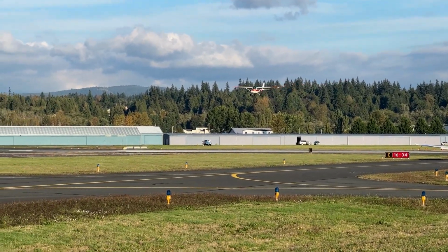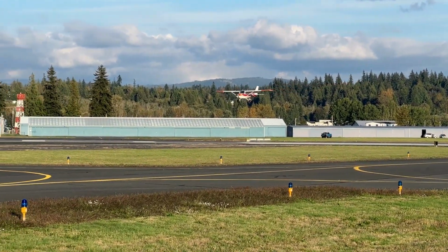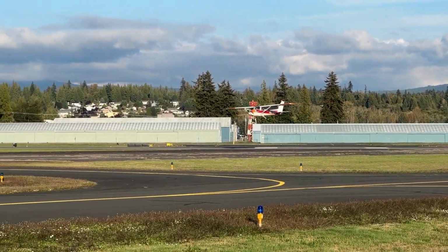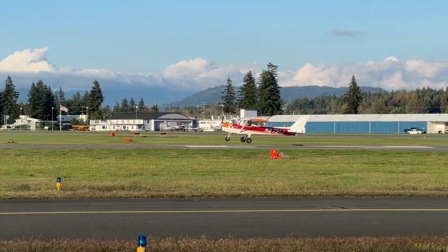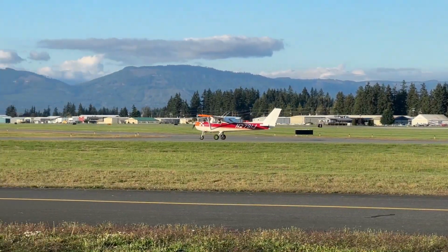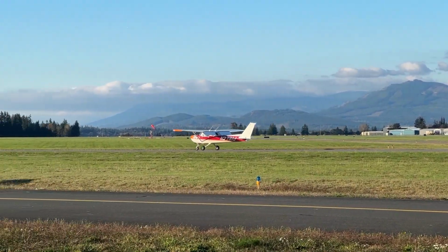Finally, let's talk about landing the aircraft. General guidance: it's just slow flight over the runway. Make a stabilized approach to the numbers and transition to slow flight just over the surface. Put your eyes down the runway and focus on maintaining control of flight all the way until you are fully stopped.